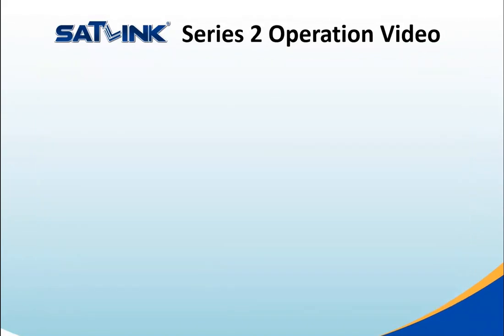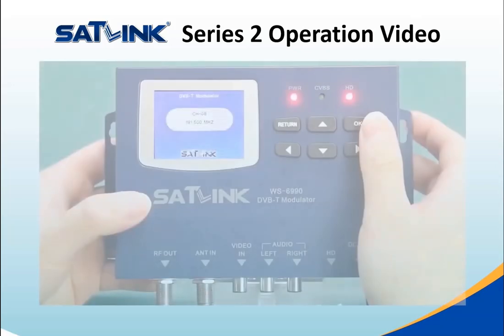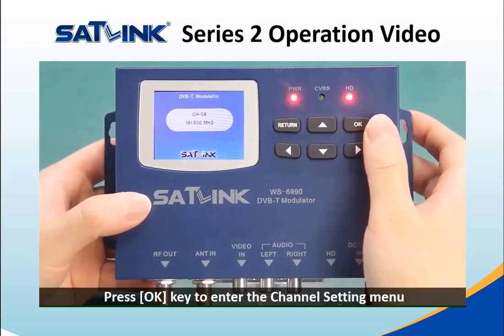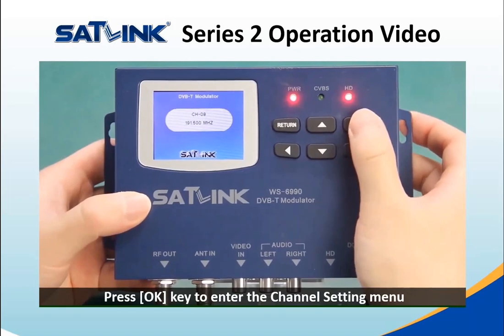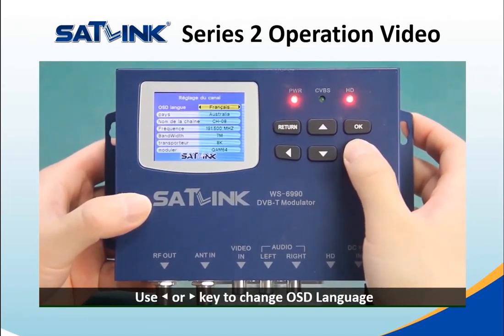SatLink Series 2 operation video. Tips. This video takes the DVB-T modulator as an example, and the operation of H.264 modulators is similar. Press OK key to enter the channel setting menu. Use left or right arrow key to change OSD language.